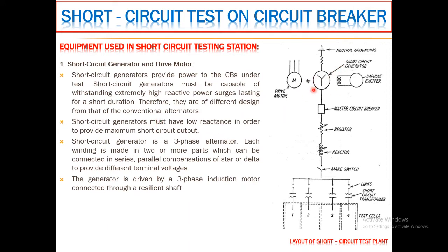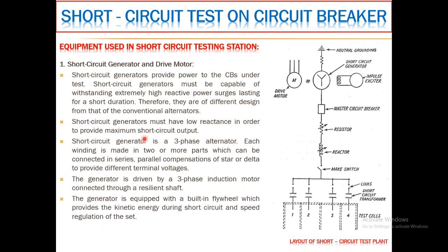You can see that the generator is coupled with this driving motor. So it is of course a three-phase induction motor which is connected to a resilient shaft. Okay, the generator is equipped with a built-in flywheel which provides the kinetic energy during the short circuit and speed regulation of the test setup, meaning this motor generator set.